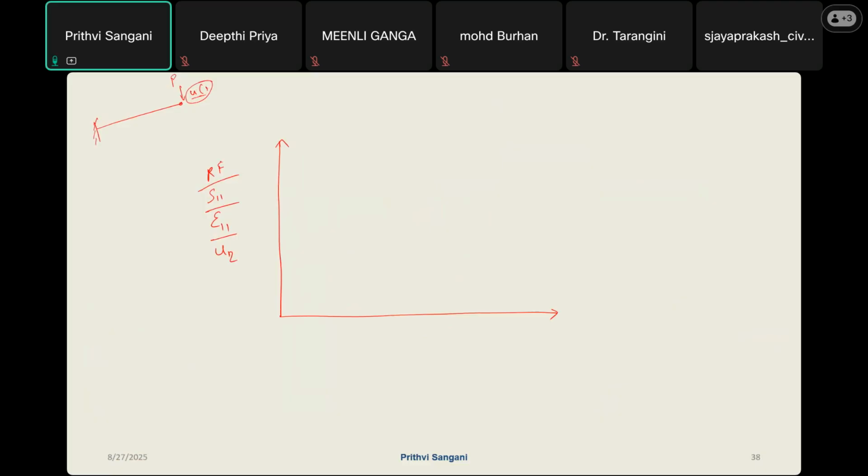So you pick one parameter which is very important for you. If you think your reaction forces are important, you can pick that parameter, and you can keep increasing and decreasing your mesh size.